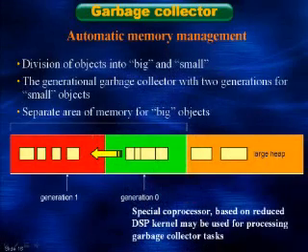The type processing engine includes 2 units: the type compatibility engine, or operating type checking unit, and the type setting engine. The sources of the units may be a type tag from memory, from the register file, from the meta-information cache, or it can be an immediate value for type comparison.